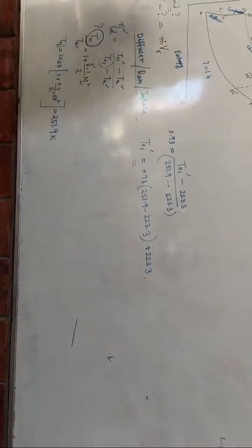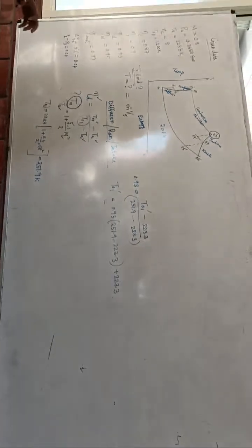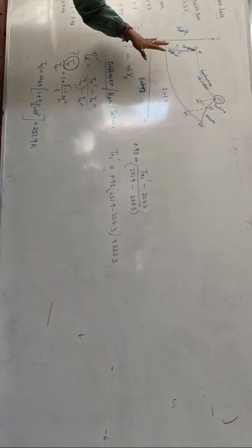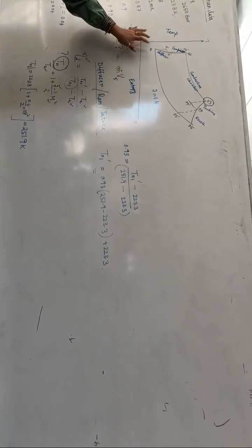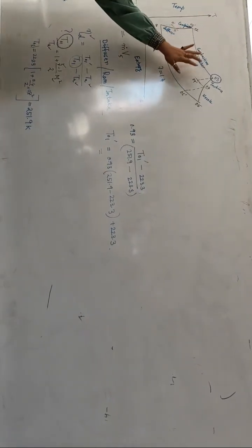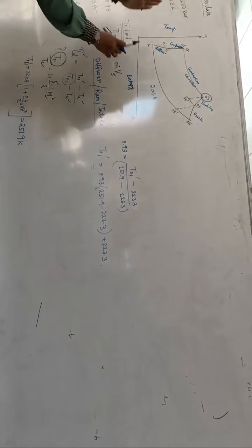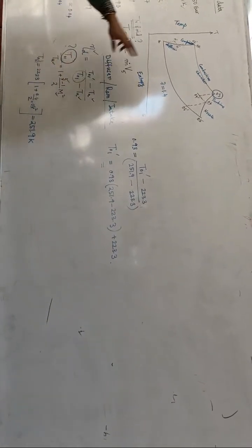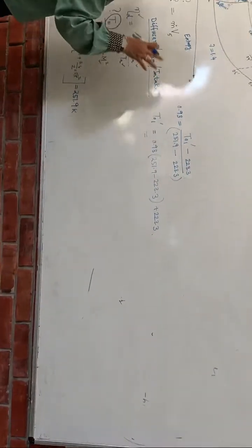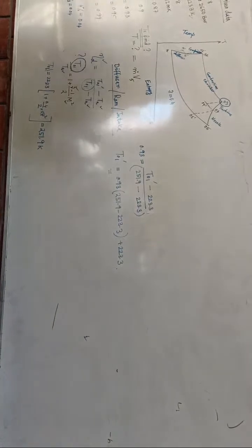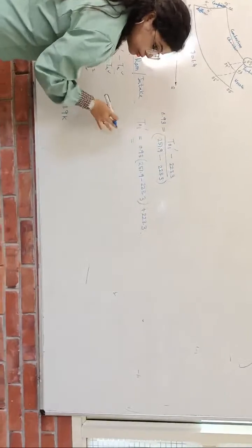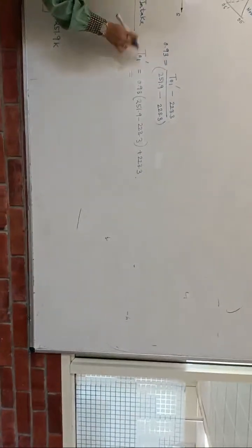Now what you have to do, for each and every component, is find the inlet and outlet temperature and pressure. For the diffuser, compressor, combustion chamber, turbine, nozzle, as we go along the flow, for each segment you have to find the temperature and pressure, the unknown factors that are not given in the data. Meanwhile you find that, I will move to the pressure for this diffuser part.